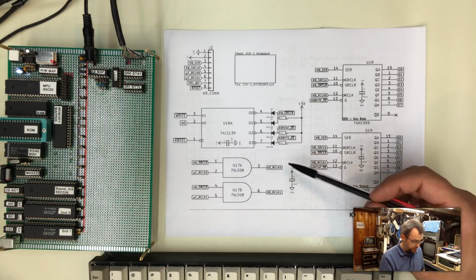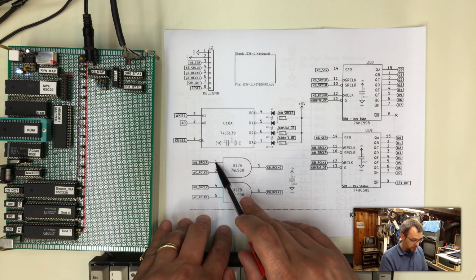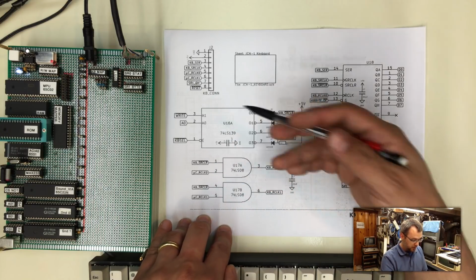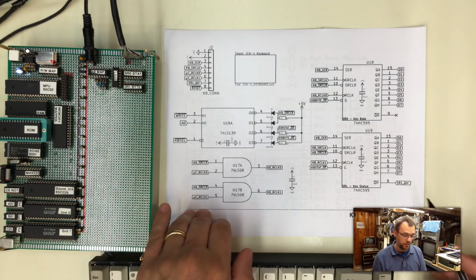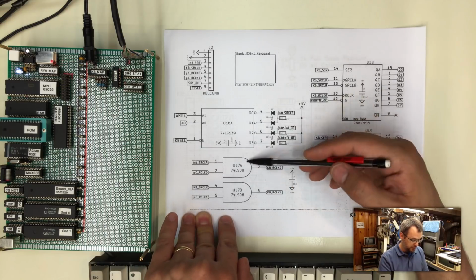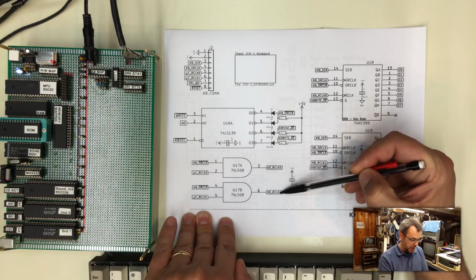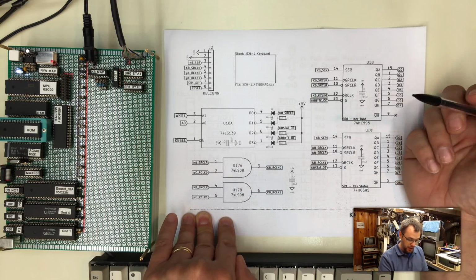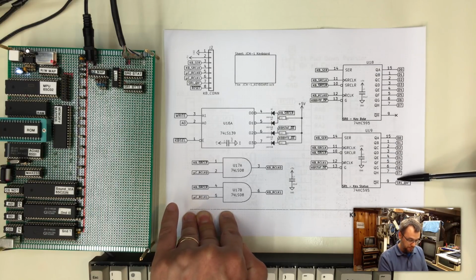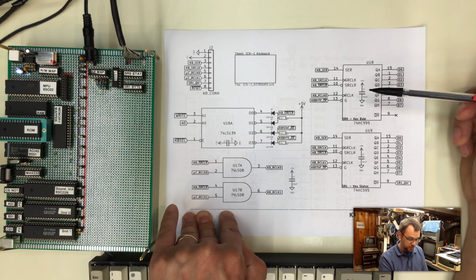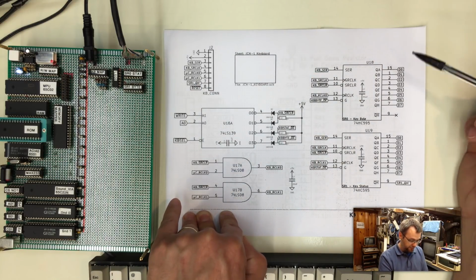This logic here is the same. This is the LS08. This is just our logic circuit here, because I don't remember what my logic circuits are, that combines these two signals so that when both of those signals are active, the keyboard is being clocked only at that same time, effectively. And of course, our 74HC595 registers, our two registers for our key byte and our key status, again, those aren't any different. Those are the same as they were before.